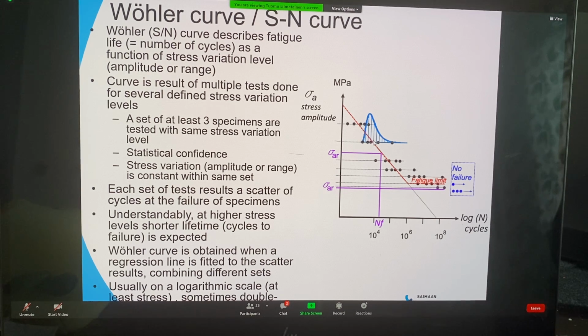Now we already have 2 points, and we could start writing a curve between these and start to extrapolate where we could see what could be the lifetime for different stress levels. But of course, 2 stress variation levels is not enough to gain enough confidence. Then we perform a third test, again 5 results, and find somewhere the average.